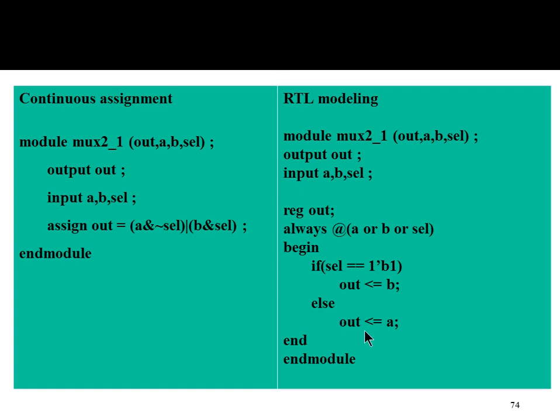But at the end of the day, we said that we would use non-blocking assignments for all design-related Verilog description. That is why we would use non-blocking assignments even in case of combinational circuits. And this representation in Verilog also is a non-blocking assignment. Okay, so you can note down this example. This will be one of your example designs that you can write a test bench for later on. You only need to note down the behavioral description. You don't need the other two, data flow. If you want, you can note it down, but you don't need it.